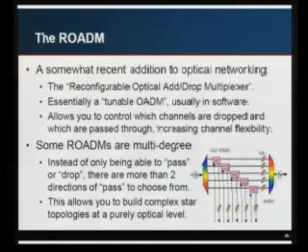The slightly more advanced variant of that is called the ROADM, the reconfigurable optical add-drop multiplexer. It's basically a tunable OADM, generally controlled in software. Instead of the hardware being manufactured to only drop a specific channel, you can control, usually in software, which channels you want to drop, and that increases your channel flexibility. So you no longer have to be very precise on what channels you build your OADM for, what channels you plan for, or what channels you keep in inventory. You get a lot more flexibility.